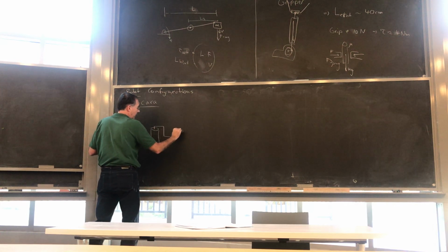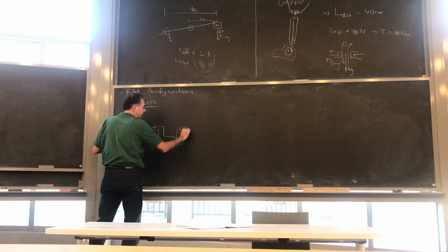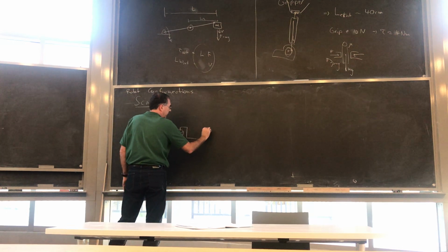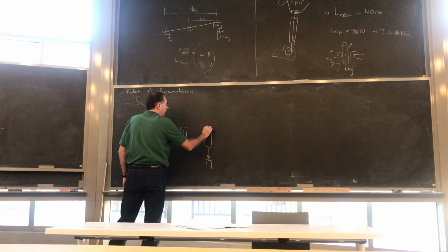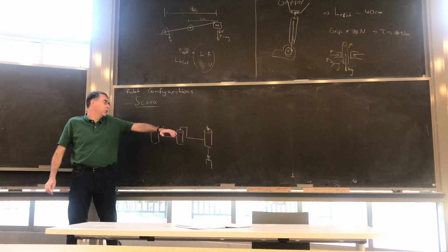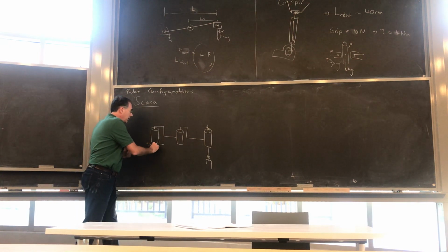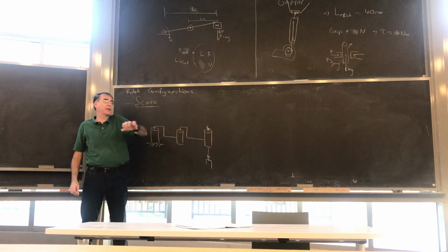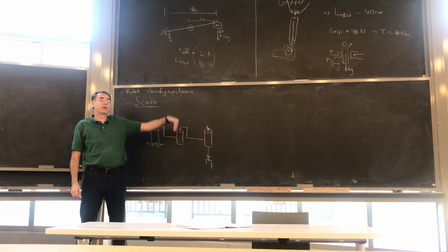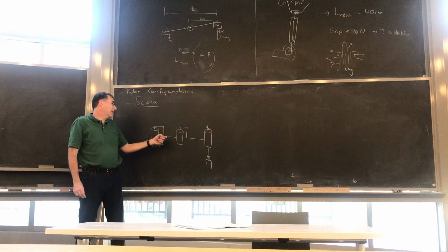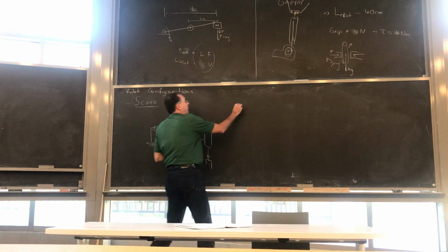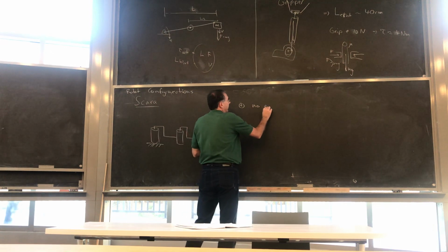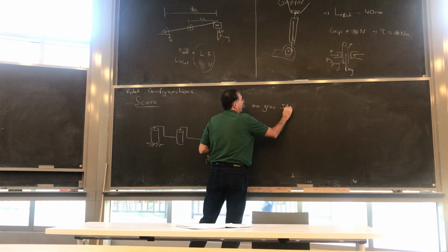But basically, an original SCARA looks like this, where it has an up-down linear one in the back. And so it moves the first 2 motors in the horizontal plane, and then the last motor goes straight up and down. And the reason they do that is exactly for that reason. So the big pro is that there's no gravity load on J1 and J2.